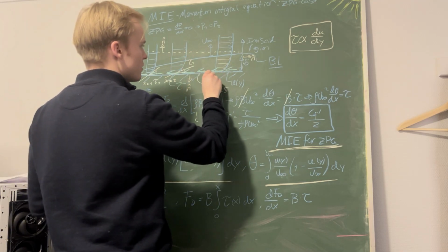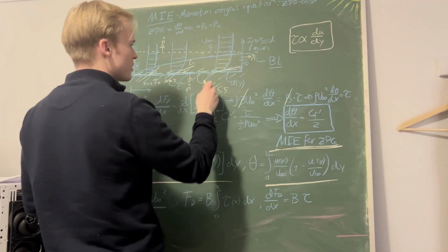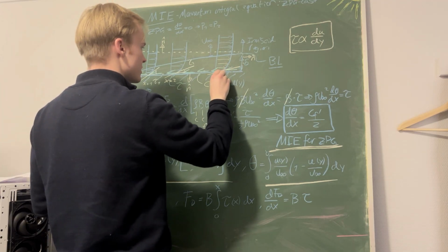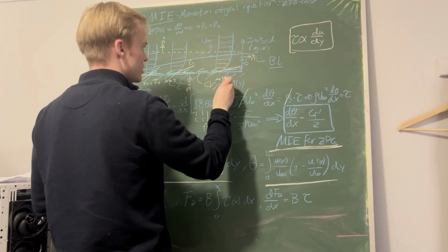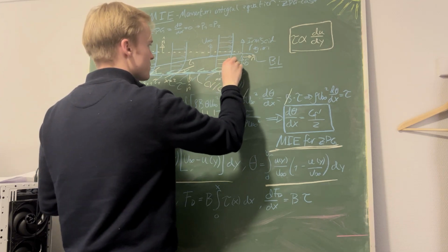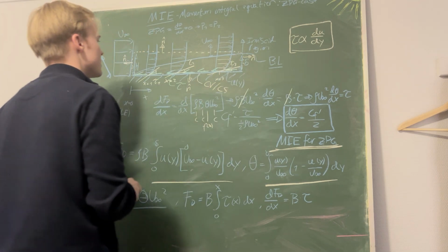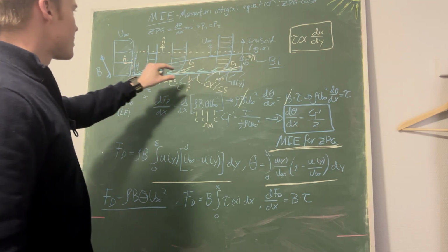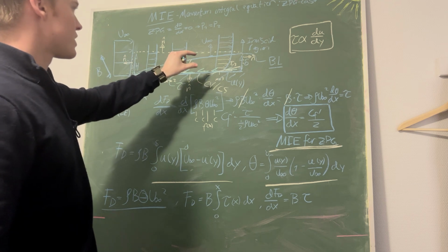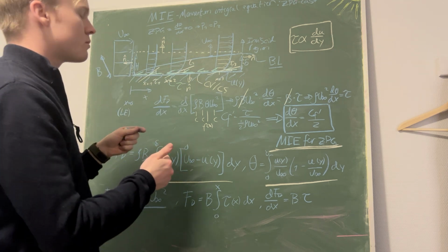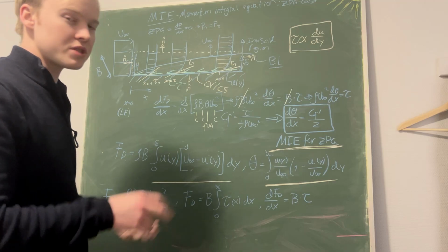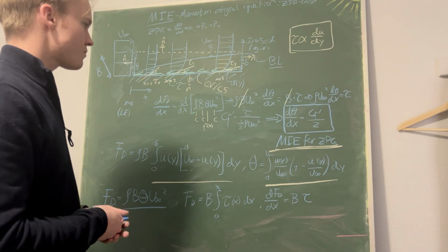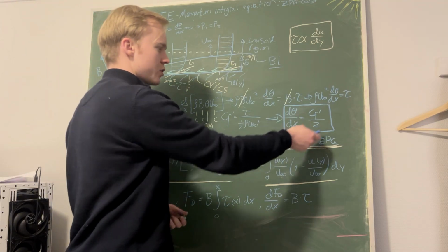And then here the gradient is even steeper at this x equals 3 location. So we see that the shear is increasing with our flow moving in the x direction. So it's basically taking away momentum, or you could say energy, from our flow.